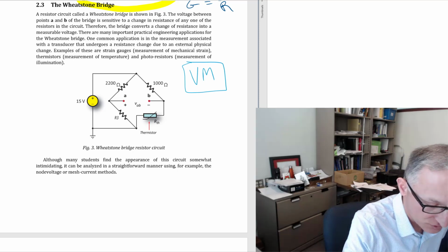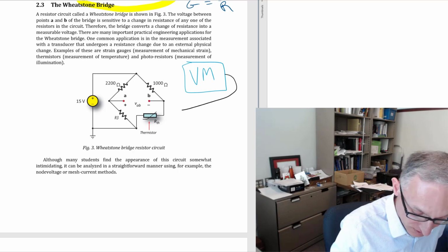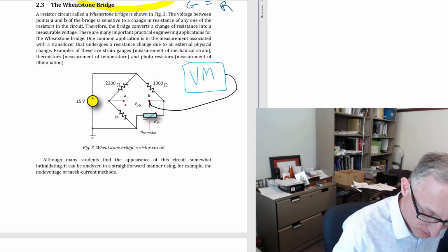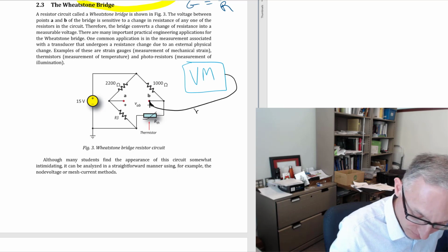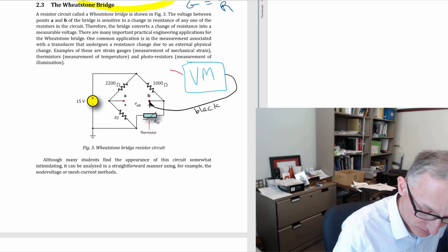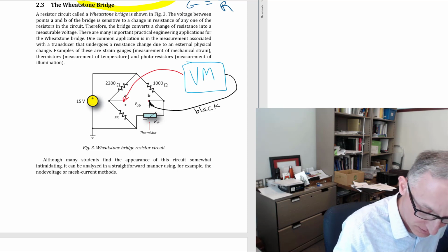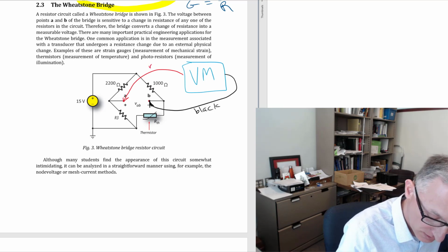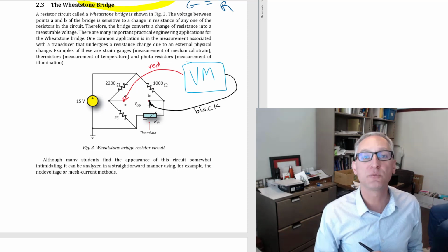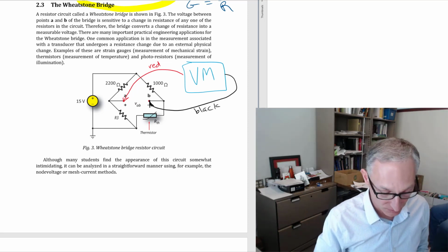So what that actually means is that the black lead is going to come around and connect to B, okay? So this is the black lead. And then the red lead is going to come around and connect to A, okay? That's the positive. So that's how you would hook up your voltmeter to make a measurement VAB, like so.